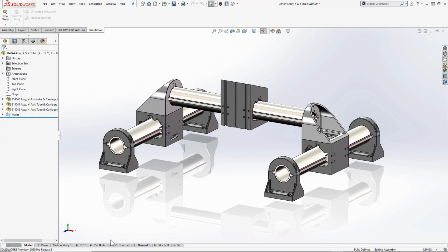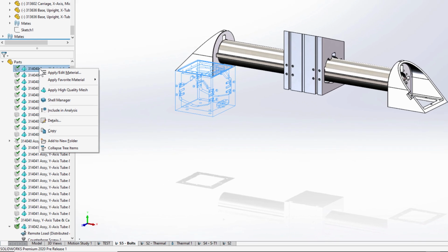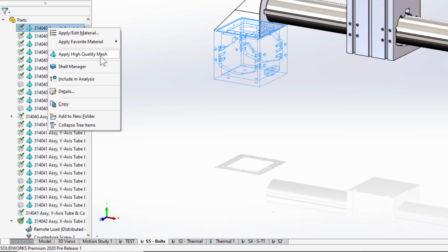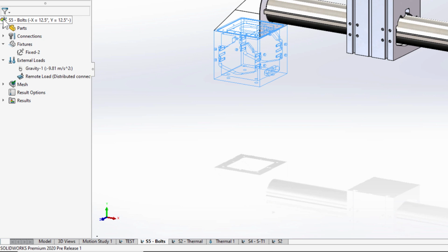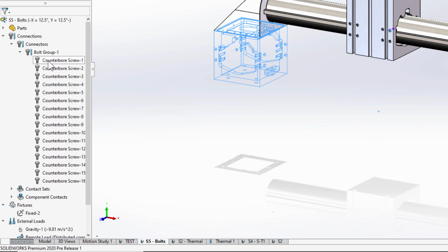The first thing comes from the mesh. It's necessary to use appropriate mesh element types to get good solve times. 2020 actually gives us the ability to choose between a draft and high quality mesh on a per part or per body basis. So we can run larger simulations in shorter amounts of time, but ensure we're getting high quality results where we need them.